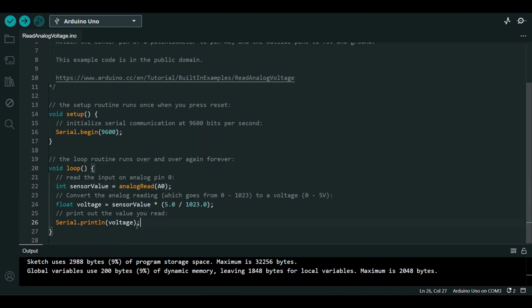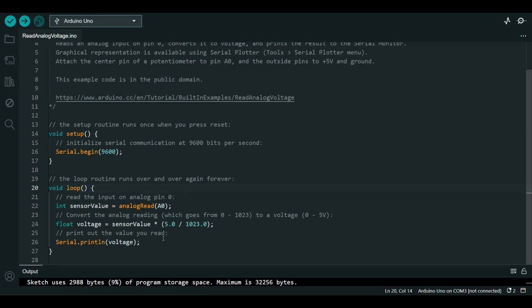to the pin. In the program below, the very first thing we'll do will be in the setup function to begin serial communication at 9,600 bits of data per second between your board and your computer.